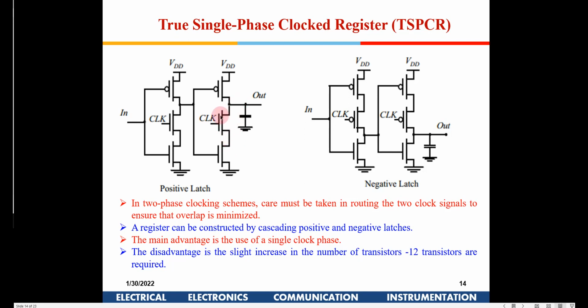That is because NMOS is a perfect transmitter of 0, and hence if you connect it here, there won't be any problem, because this is a PMOS which is going to pull this node to high. Whereas when we are using a PMOS out here, we are taking the output from the node below the PMOS, from the drain of the PMOS, so that it gets charged. You will get a full rail to rail output at both these two nodes.